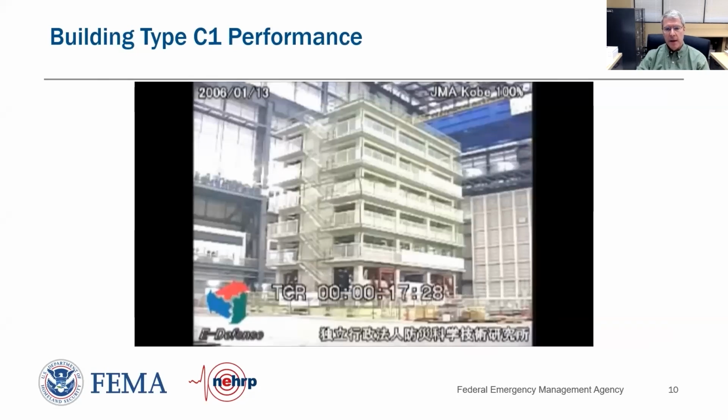This is a video that we're going to walk through. It shows 2 building types. It shows performance for a concrete moment frame, C1, and it shows what a concrete C2 or shear wall building, how it behaves, and the drastic difference between the two. Now, the video is of a 6-story concrete frame building built on top of one of the largest shake tables in the world over in Japan. And this is the E-Defense Lab. They're doing some great work over there.